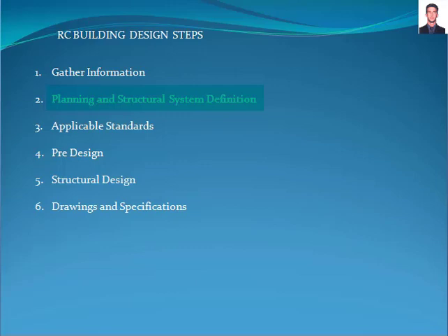Talking about the location of columns, beams, or shear walls, this is one of the most important factors. We define the structural system and structural cost of the project. Column location will define the span of the slabs and beams. Slab span will define the type of slab to use that will affect the weight and the cost of the structure.